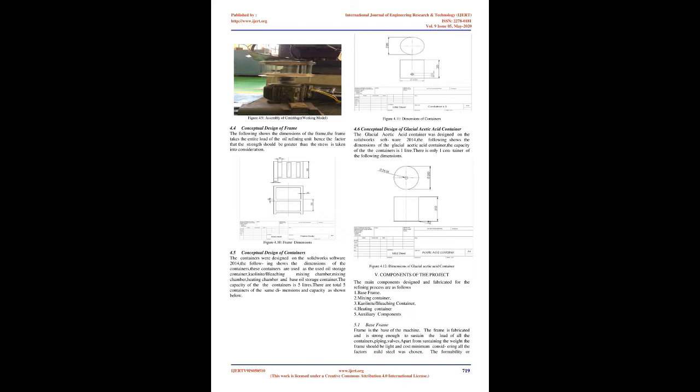At this stage the oil is heated to a temperature of 120 C and then transferred to the mixing chamber, where activated charcoal is introduced and mixed for about 10 minutes. It is then allowed to settle for a period of 10 minutes, followed by centrifuging at 3000 rpm for a period of 1 hour, wherein the residue settles at the bottom, which is then discarded, and a dark red transparent base oil is produced. It is then stored in the base oil container.